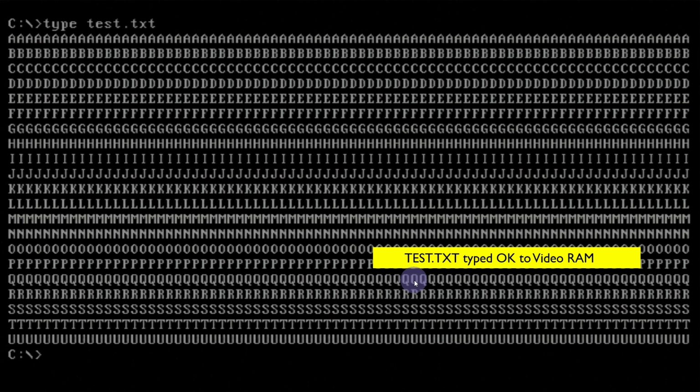Now, one of the other tests I've done is actually with the video RAM loaded with this data. What I've done is I've dumped the video RAM into SREC format. And the strange thing I was finding is that the data being read out of the RAM again is getting all messed up. So if you just have a quick look at some of the SREC output from this here, we should actually see that we've got all the characters A, B, C. So A is 41 hexadecimal, and the attributes for each one should be consistent, but in fact what we'll see is that this has actually got quite messed up.